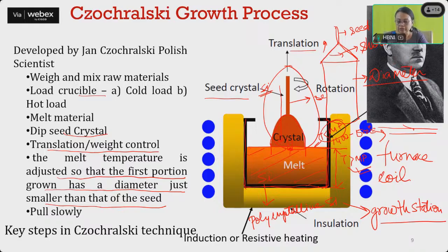When we come to silicon crystal growth, as I told you on the first day also, generally the diameter of this crystal is around 6 inches to 12 inches. 12 inches diameter means 1 foot. So you can imagine the size of the crystal. It is around this much diameter crystal that is grown using the Czochralski technique. So the question is how we are maintaining the diameter of the crystal, and the length of the crystal is even 3 meters. I will be showing you a few video clips where you can see how it is maintained.